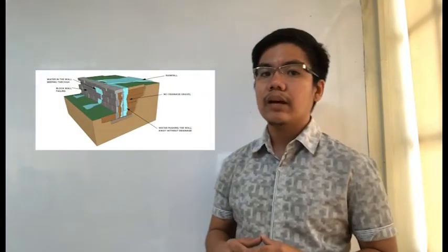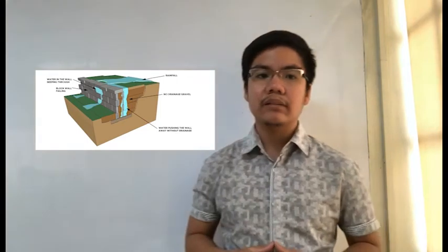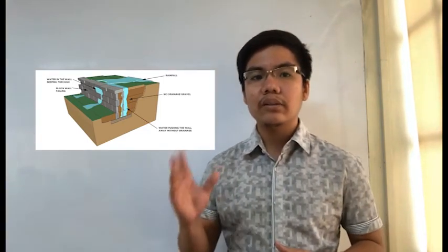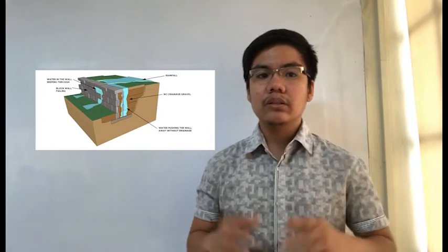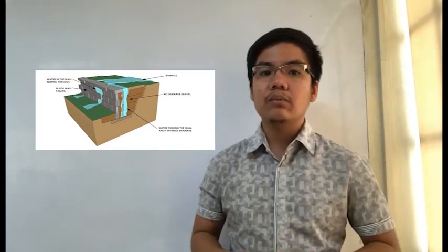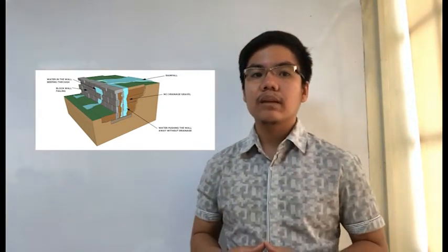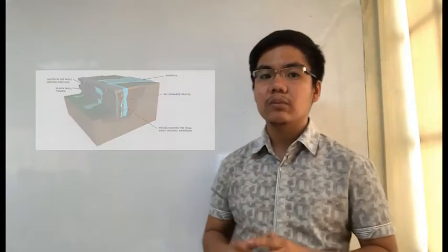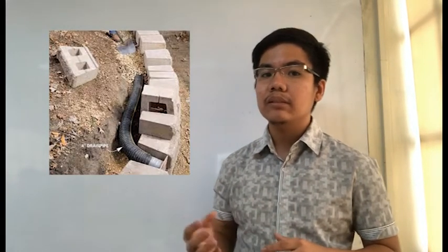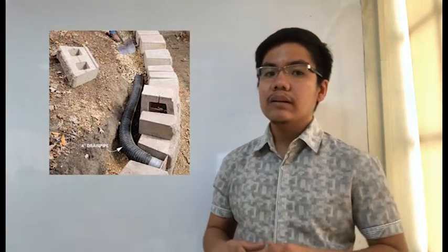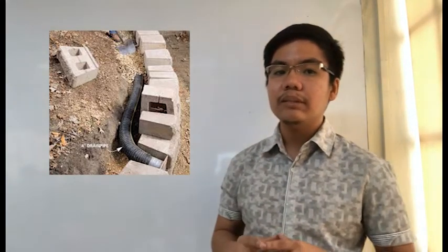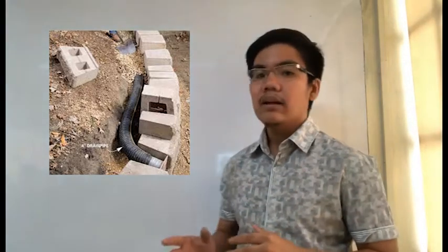Also, groundwater behind the wall that is not dissipated by a drainage system causes a hydrostatic pressure on the wall. The total pressure or thrust may be assumed to act one-third from the lowest depth, or for length stretches of uniform height. Unless the wall is designed to retain water, it is important to have proper drainage behind the wall in order to limit the pressure to the wall's design value. Drainage materials will reduce or eliminate the hydrostatic pressure and improve the stability of the material behind the wall. Dry stone retaining walls are normally self-draining.